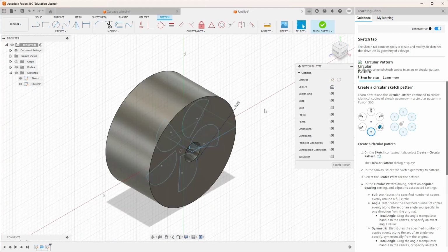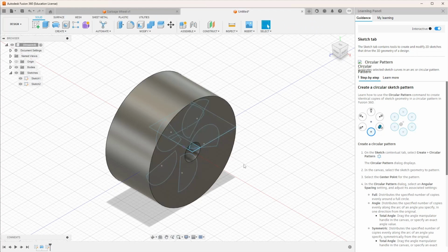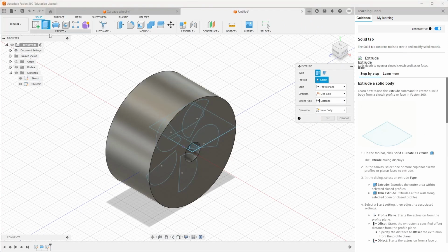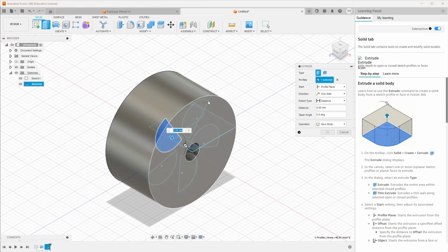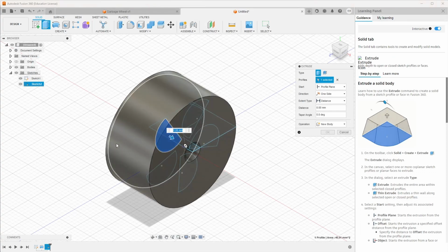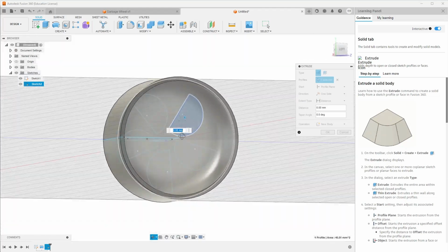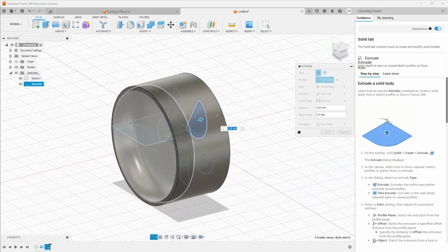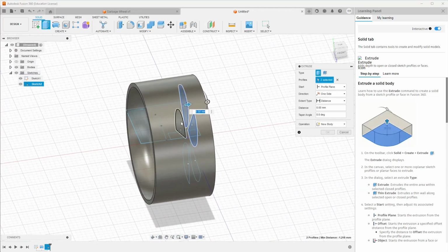These shapes are going to show up on that middle plane again. So what I'm going to do is I'm going to finish the sketch and I'm going to extrude out these shapes here. If I can't really get a hold of them, sometimes I'm going to have to modify how I'm looking at my drawing so I can grab them easily. Right now, it likes that.